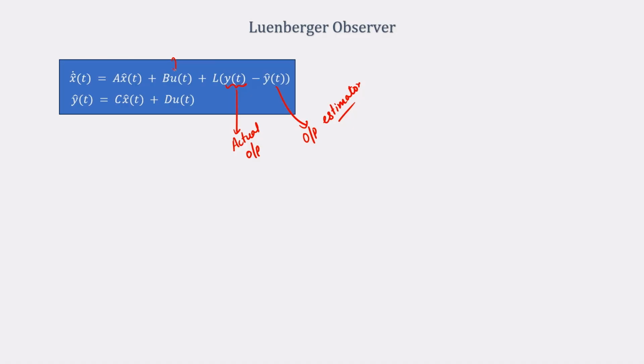What the inputs to that system are will depend on what type of observer you are using. For example, when you are using the open loop estimator, the only input going into the observer is the u information. However, when you are using a Luenberger observer, you can see from the differential equation that not only u, but y will also go as input to the observer.